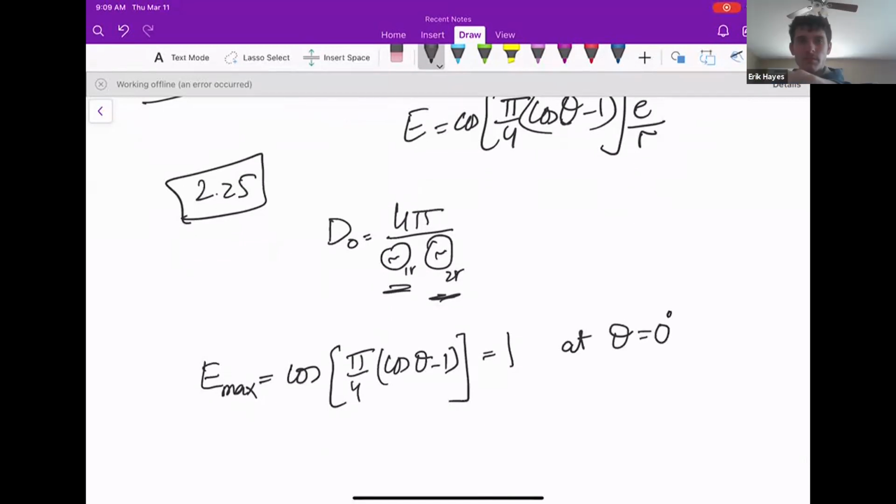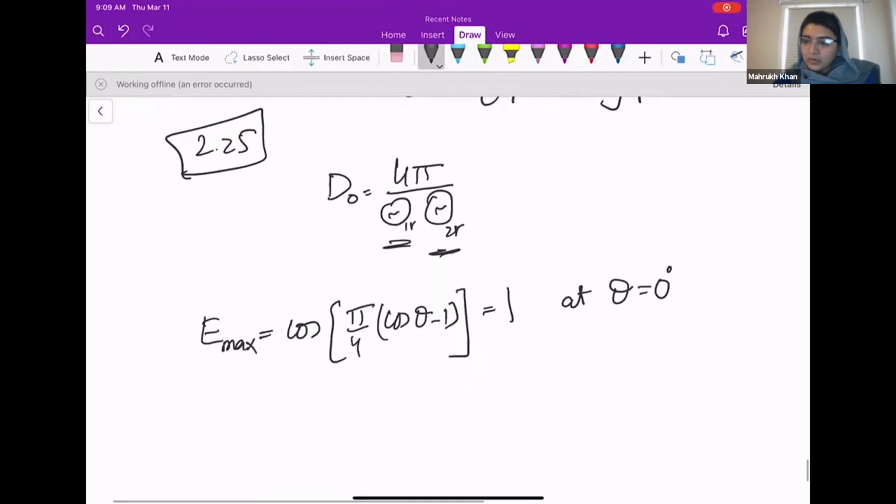Directional. It's directional. So in that case, when you find half power beamwidth, you do not have to do 90 minus something. The half power beamwidth is a true half power beamwidth. In this case, because this is E and not intensity, it will be not 1/2, but 1 over square root of 2. And then you can just